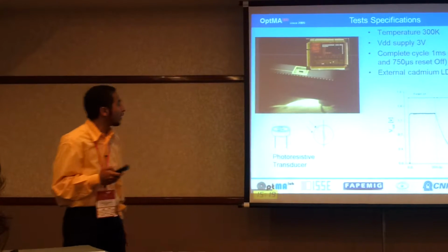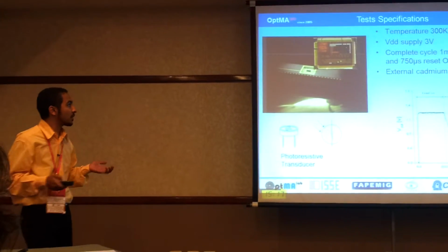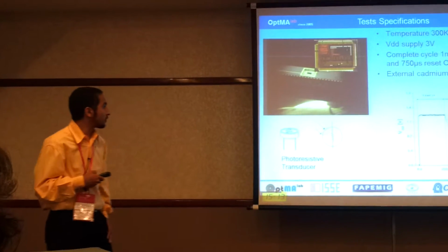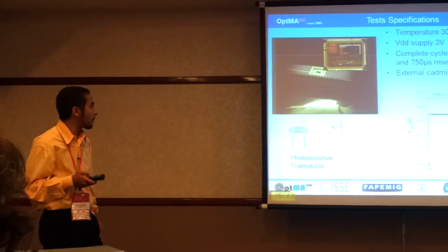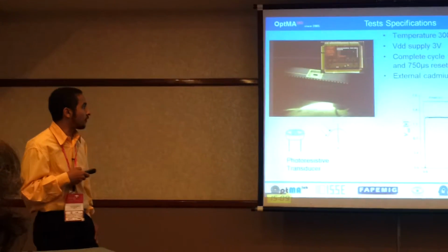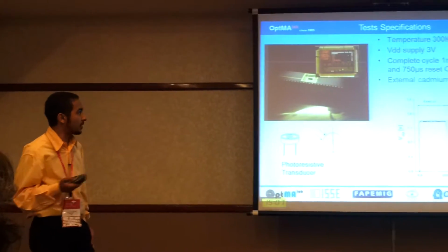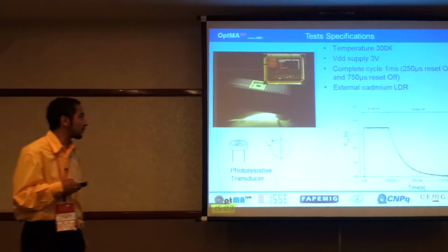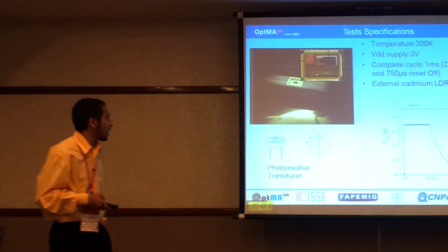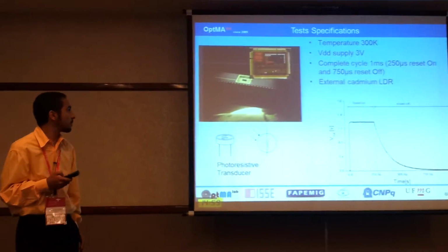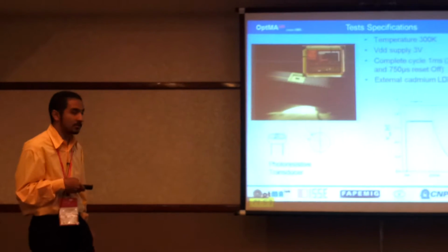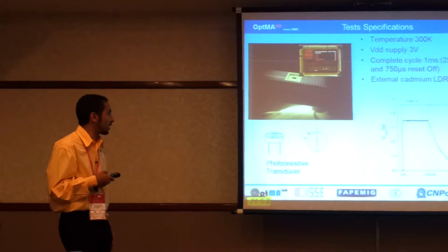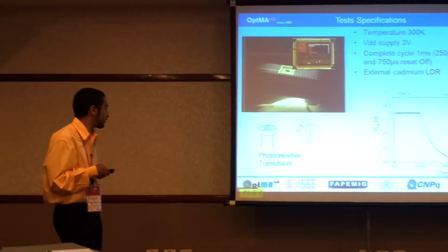The test was performed at 300 Kelvin with a 3 volt supply and a complete reset cycle of 1 millisecond: 250 microseconds of reset on and 750 microseconds of reset off. An external cadmium LDR was used as the photoresistive transducer.